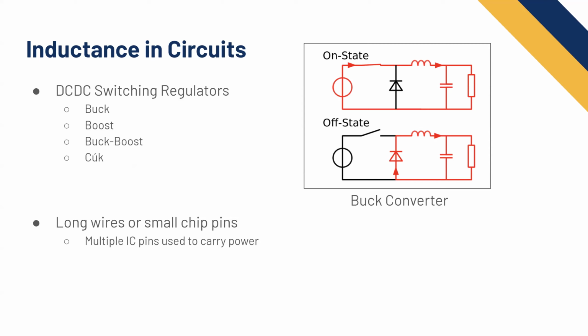Or smaller chip pins, like if you have a smaller radius conductor, the inductance is worse. So this is why when you're looking at ICs, usually they have multiple pins to carry power and ground because that's a high current signal. And so they have more of them because inductors in parallel will divide based on the sum of the reciprocals. All right, any questions on this?